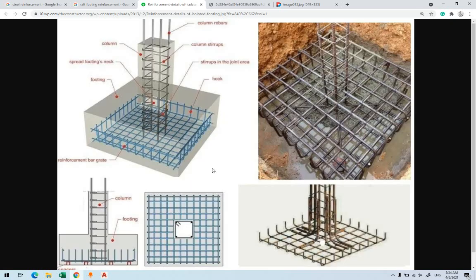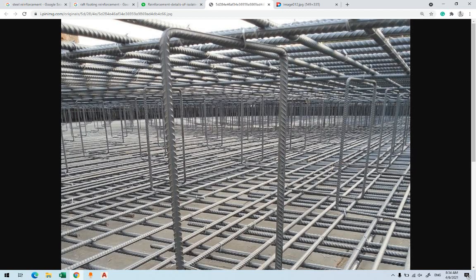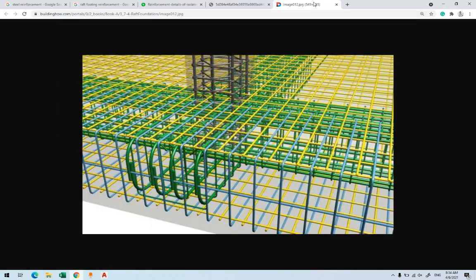Why? Because for a single footing, sometimes they don't even put any chair. Or they may just put 1 chair or 2 chairs, or maybe even 4. If it is a bit big, they might just put them in the corners in order to make it stable. But for the mat foundation, because you have a big area, you have to put these chairs and calculate them as numbers the way they're given there.